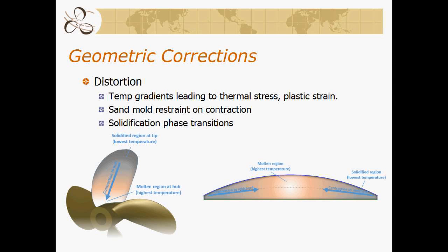The hub face offset functions the same way. If I specify 1/8 of an inch for the hub face offset, it's going to add it to the front face of the hub and the aft face of the hub. So it won't be split. It will be a true dimensional offset from the surface.